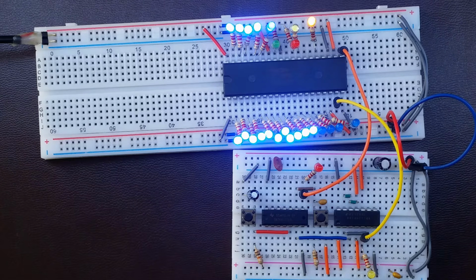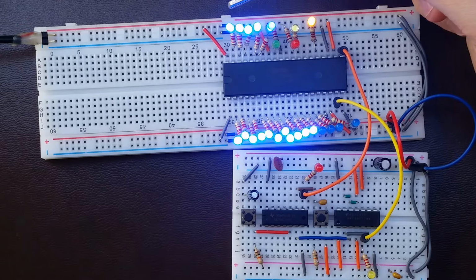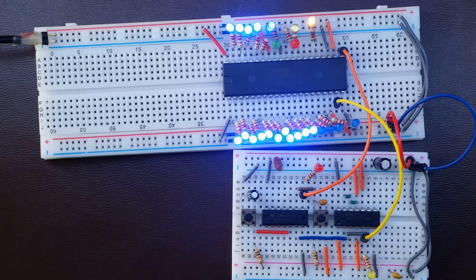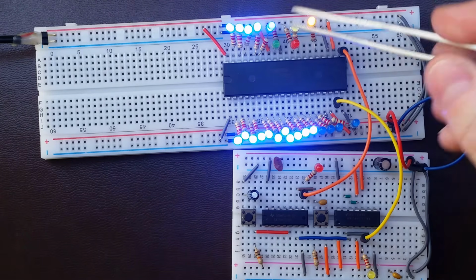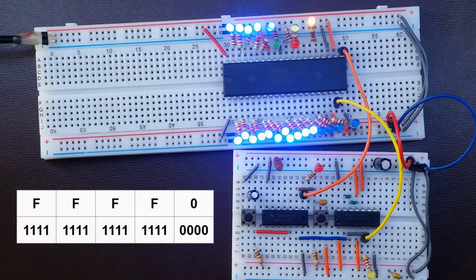We've got some address lines active. Just to remind you, the most significant bit A19 is here, then it goes 18, 17, 16, 15, and then from 14 down to A0 at the bottom part of the CPU. So we read the address anti-clockwise. Do you remember when I said what's the address the CPU tries to read to start its program after reset? It was FFFF0